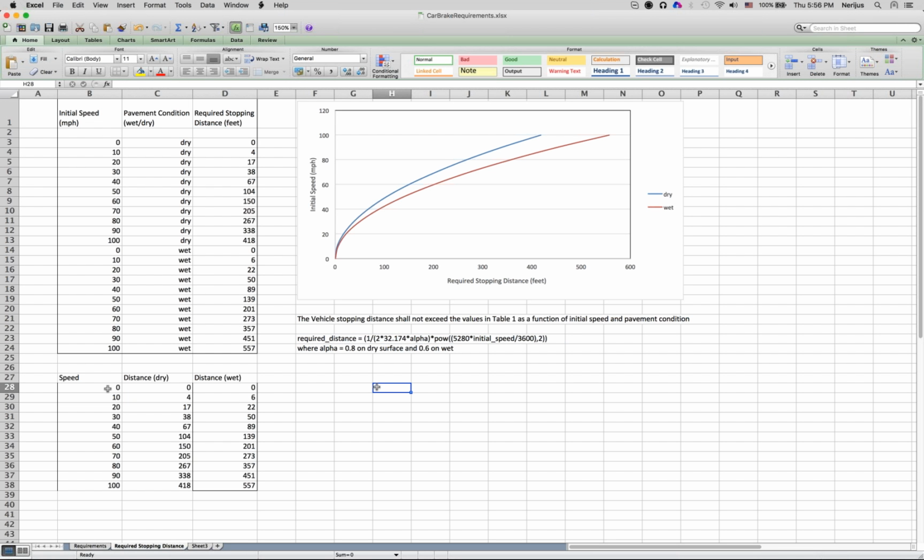But you can also import initial data, like vehicle configuration data, from Excel. Since MagicDraw version 18.1, I think, we have copy and paste. You can simply copy data and paste it into a MagicDraw generic table, in which you pick the element type and the columns you want to show.